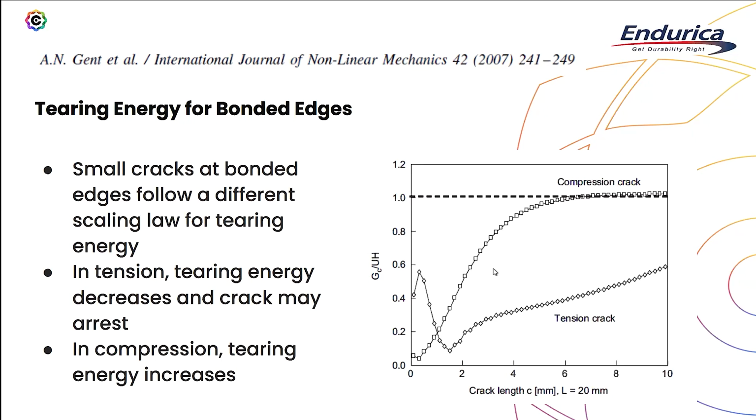On the other hand, if that bond edge is loaded in compression, then it's going to keep going up like we might normally expect. So again, just a recommendation that if you're looking specifically at a bonded edge with a singularity, you're going to want to look at how the tearing energy scales with crack size a little bit more carefully.